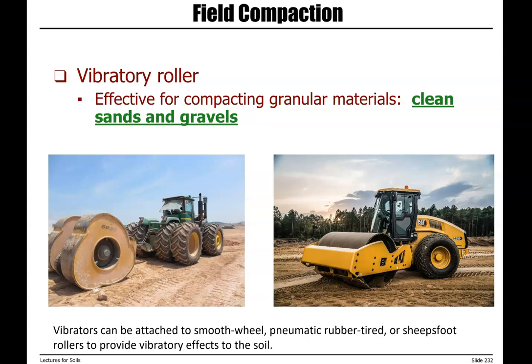Another group of compactors is vibratory compactors, or vibratory rollers. These ones have a different technique. They use vibration to move particles along each other. When we are using vibration, it can be very efficient when we have granular soil. This is not efficient when we have clay or fines. This is effective when we have granular material or clean sand and gravel.